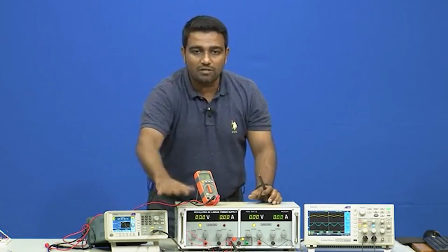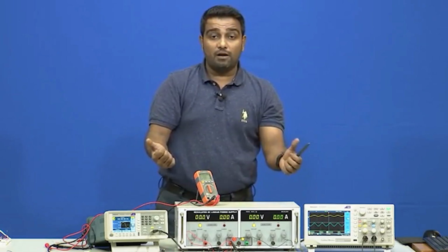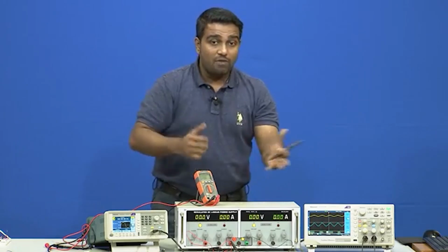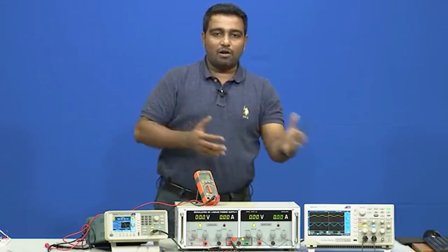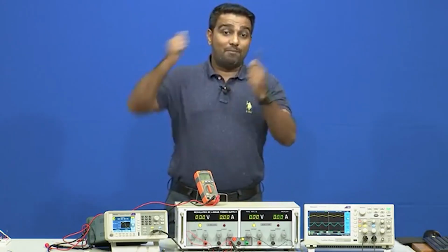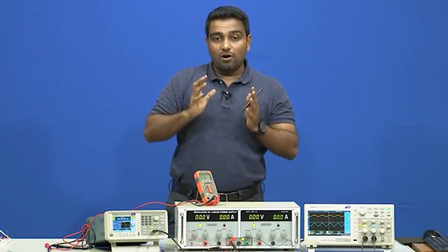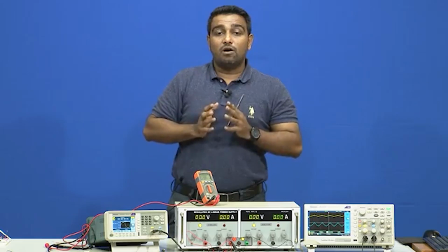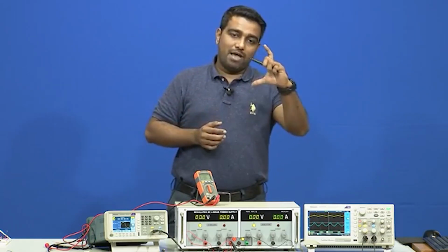Input signal given to the circuit was square wave and we were under the impression that input is sine wave, and wondering why the output is square wave. So, we have to understand, if the input is something, we cannot expect output which is different than the input signal, we can only amplify it, right. But we can also see clipping, which is there when the amplification or the gain of the voltage is more than the bias voltages.